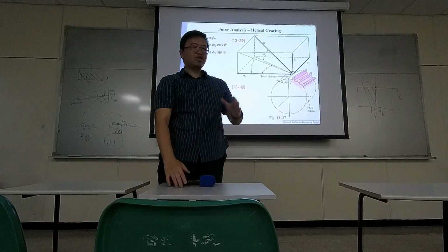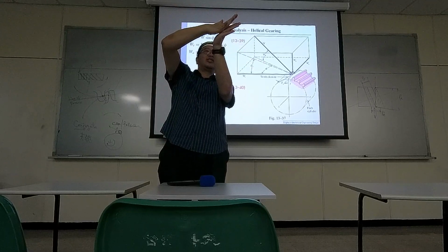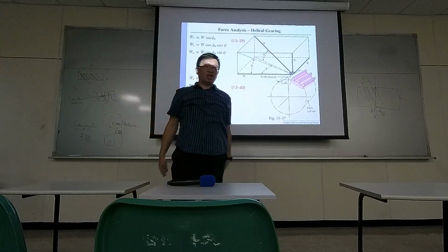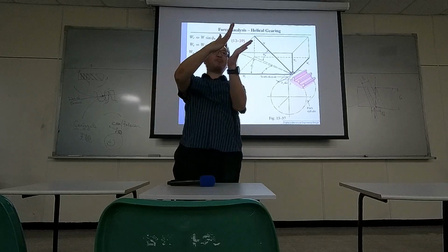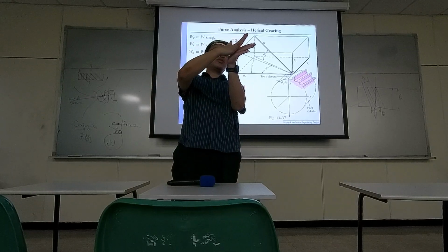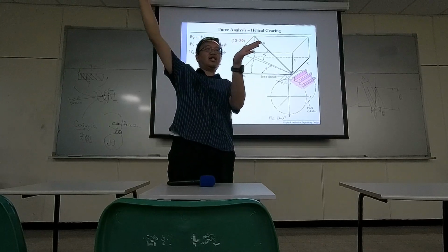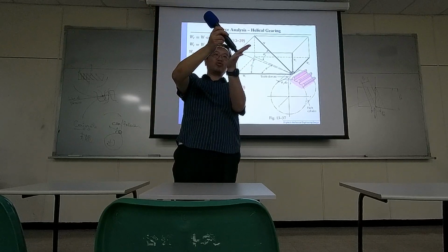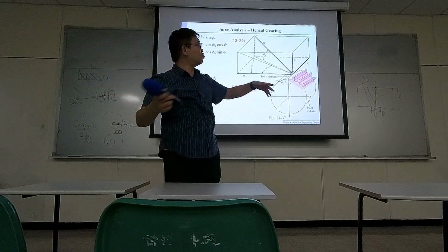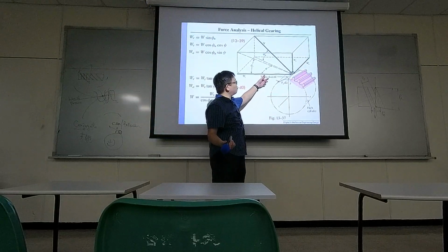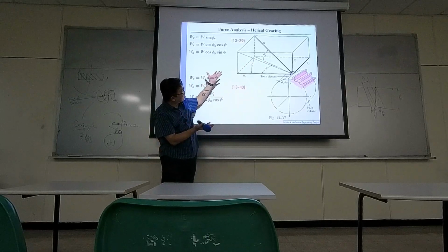So the force that is applied from one side to the other follows a certain direction. You have two tooth profiles, and let's say our classroom is our coordinate system x, y, and z. The contact point between the two teeth for helical gears will be somewhere in space, and the force is normal to the surface, so that force vector is not parallel to x, y, and z. That's why we need to compute the force components along x, y, and z in this configuration.